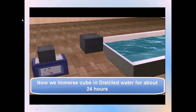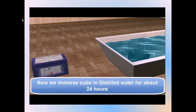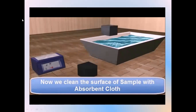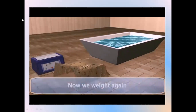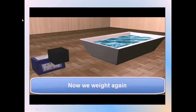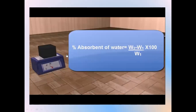Then it is put into distilled water for 24 hours without any disturbance, so that the stone is completely immersed, all the pores and holes are filled by the water, and the stone becomes 100% saturated. Then the stone sample is taken out and cleaned with a cloth so that the excess water on the surface is removed. Now again the stone piece is weighed, called W2, and the water absorption is found out.